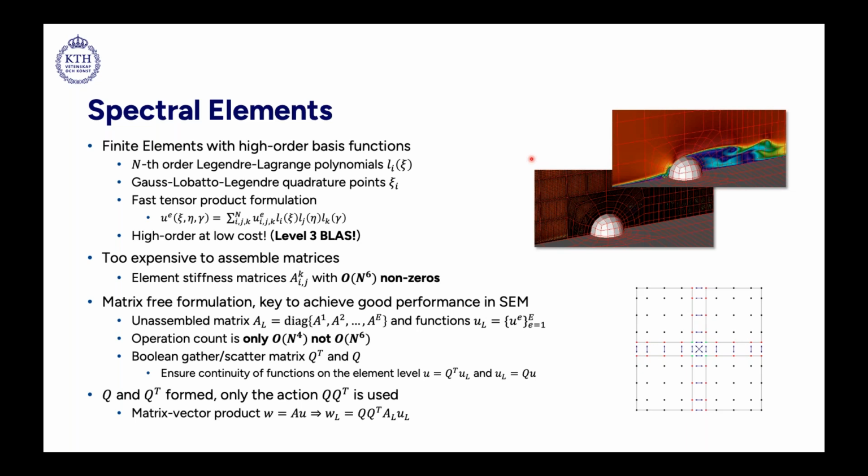Compared to other codes like high order finite volumes, our communication stencil between elements in spectral elements is only of unit depth, which means that we only need to communicate a very small fraction compared to high order finite volume codes, for example, which have a very wide communication stencil due to all the ghost points.